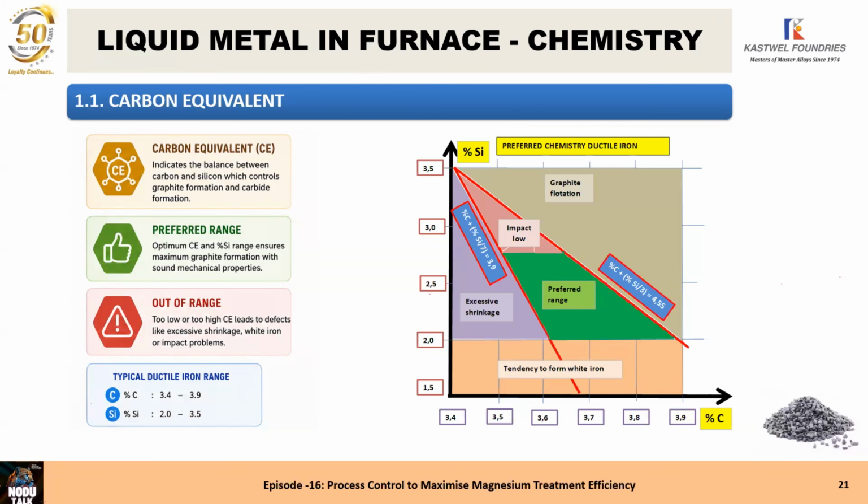The tapping temperature depends directly on the pouring temperature. If the pouring temperature is 1390 to 1410, and including the tapping time, deslagging time, and traveling time with the ladle, treated metal pouring into the pouring ladle, all of it matters, no, sir? Yes, it does. So to maintain my pouring temperature, I require to keep my tapping temperature in the furnace higher, considering all the losses in the process. You have answered your own question. How will I restrict myself to 1450? That is one question, sir.